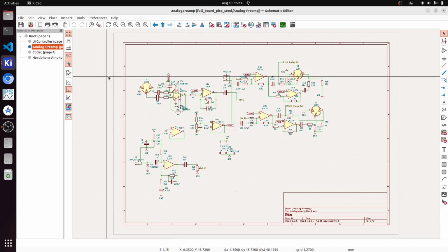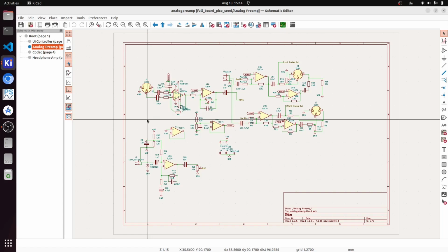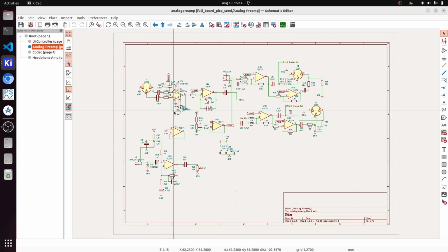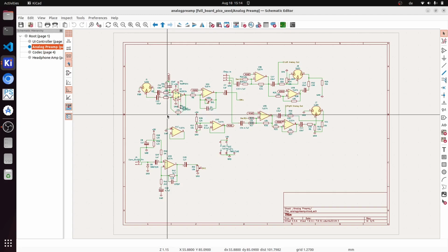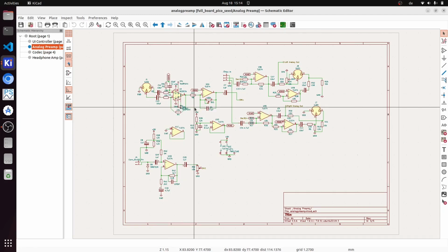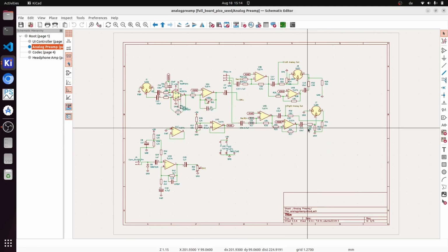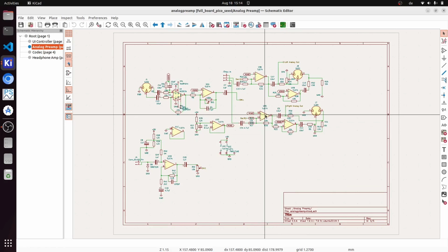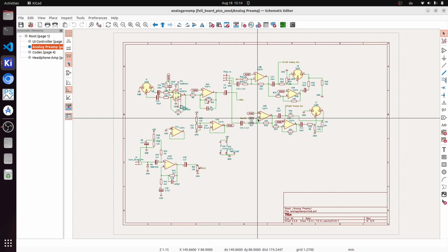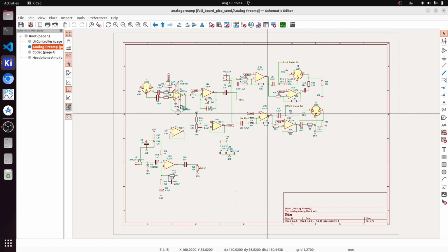The analog preamp shows different sections. Here we have the microphone preamplifier part, which is built around the NE5534 op amp, which is a pretty common design in many pieces of audio equipment. There is nothing special about this. And then we have the output stages here. This is a stereo out, so we have 2 times the same circuit, and the symmetrization is done electronically and not using a transformer, because I'm quite confident with working with op-amp circuits.